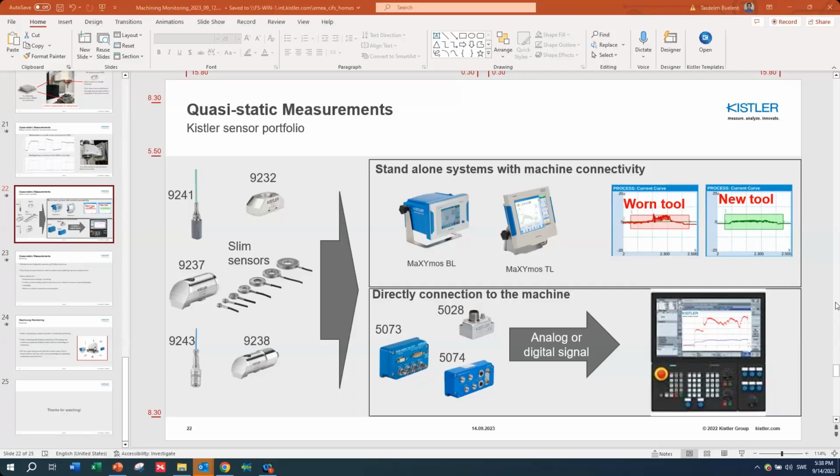You can do this in different ways, but of course we should also be humble here and say that if you really feel that you must be very close to a cutting point where you have a lot of temperature change and you cannot really conceal your sensor, and you are making maybe hours of measurement, and you really must measure the absolute force values, then maybe the piezo is not the right strategy for you.